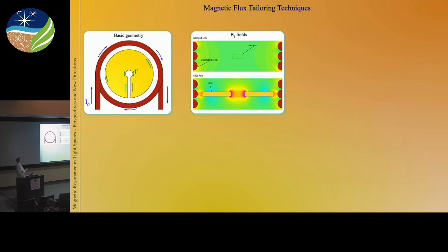And the experiment itself then works relatively straightforwardly. You place one of these lenses in plane with an excitation coil, and then you can pulse into the excitation coil. Of course, the magnetic field will be coupled into the lens because it is also a conductive material. And then we have a ring current building up in the outer diameter of our lens, which travels, for example, in that direction.